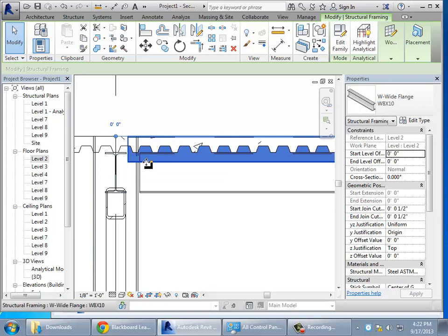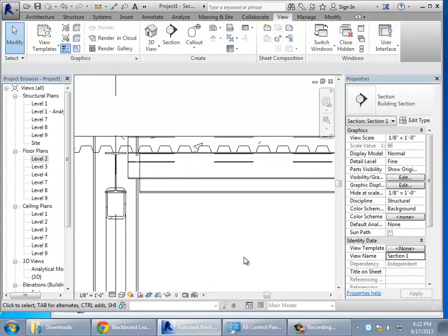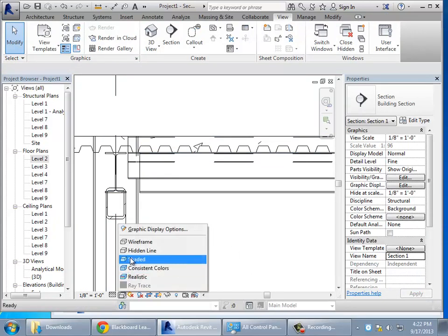Let's go over there. Oh, that's just one of those little 8x10s. That looks like as I was putting in some of my 8x10s, I didn't actually get them at the right level. That's a mistake. What I should do is actually lower those down 5 inches so that they're riding below the floor deck too. Again, I can do that, minus 5 inches. It would be better to actually go back and fix the whole system. Okay, so this really does kind of have a high payoff in the end.